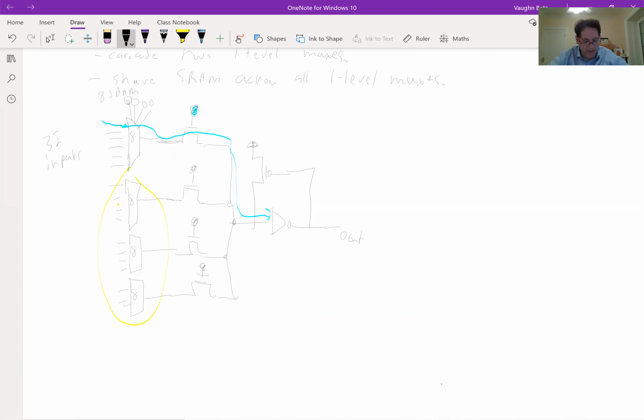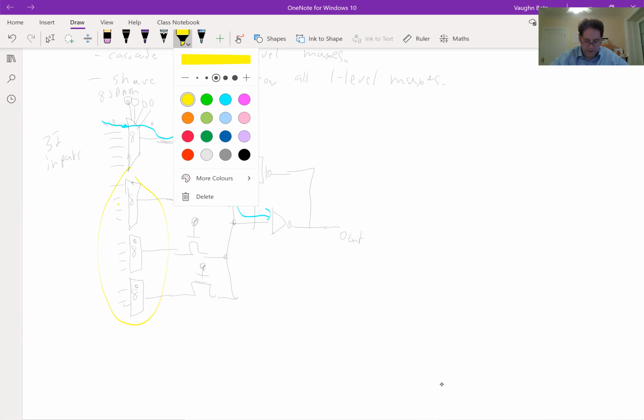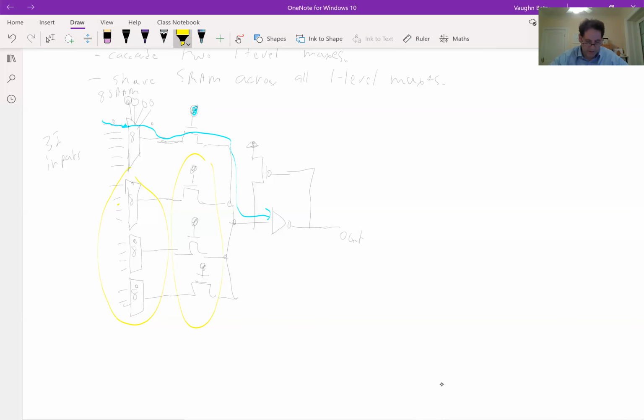And that's always true. There are always 3 of these 4 muxes that are don't care, because I want to get one of these 32 inputs. Whichever mux it feeds, I care about how it's programmed, which signal makes it from input to output, but I don't care about the programming of the other 3 muxes, because their signals aren't going to make it through the second stage of pass gates anyway. So I don't really care.